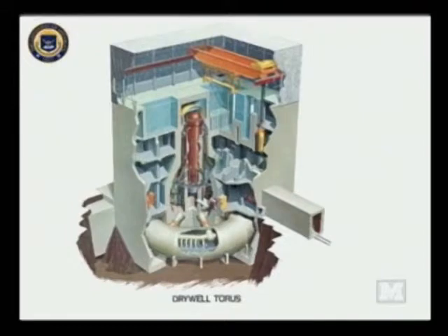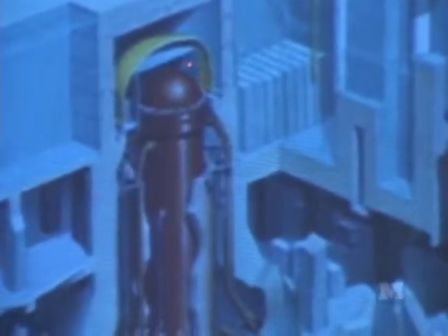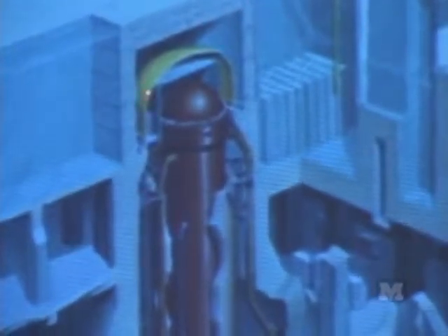So what I have here as a first simple slide is the overall picture of the BWR system, including reactor core, primary and secondary containment, and some of the safety features. This is a reactor pressure vessel, inside which is located the reactor core, and I have the next slide that will illustrate the reactor core itself, and then eventually the fuel element. And we have this yellow-colored, light bulb-shaped structure, which is the primary containment. It is a 4 to 6 inch thick steel structure, which is reinforced with several feet of concrete. And that is the primary containment.